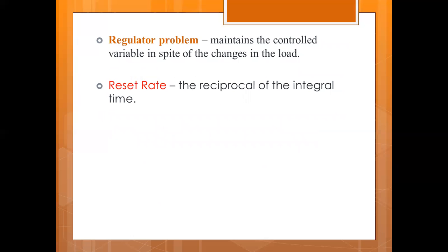Now we're on the last part on the terms. When you speak of the regulator problem, this maintains the control variable in spite of the changes in the load, or in spite of the loads to which your system is subjected. This is the usual case, the regulator problem. Now we have the term reset rate, which was discussed when we were on types of controllers. This is the reciprocal of the integral time, or the time integral. That's the reset rate.